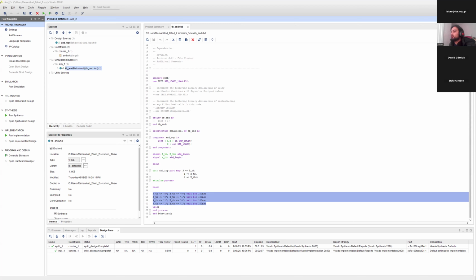If you're using a breakout board or something in your FPGA, you may want to confirm with the manufacturer what your FMC, whatever you're connecting the breakout board with. You may want to confirm with them how you're going to connect, make the constraints pretty much. And also we have an IO standard. This is basically how much voltage the inputs and outputs require. So we're just gonna do that and just save it.